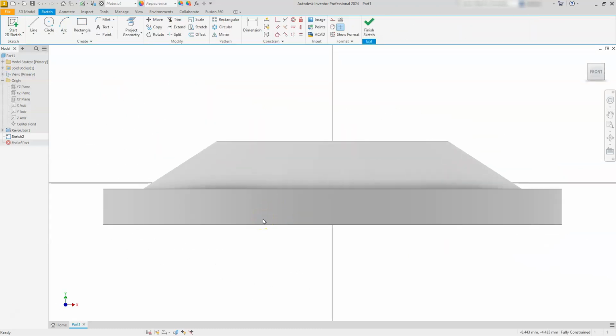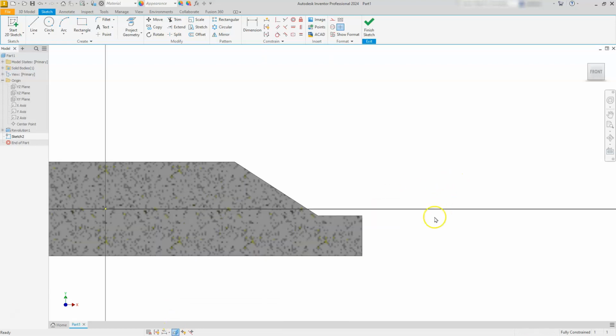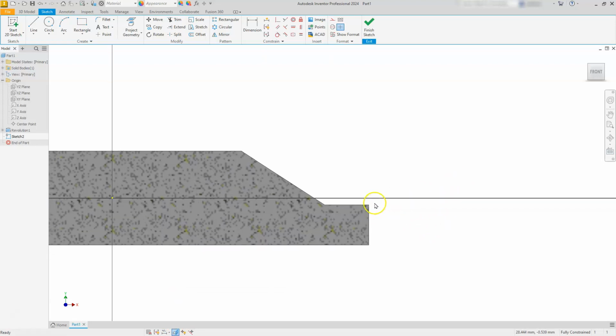And what I usually like to do is slice the geometry. So I'm going to select this icon here at the bottom, or you can hit F7. What that does is it's going to slice it to the middle. And what I want to do is create right on this endpoint, right? So that's where I want to create my line from. I'm going to start a line, and I'm going to place it at that endpoint. And I'm just going to kind of freehand sketch that. I'm going to go up here. I know that this shape looks something along this line.